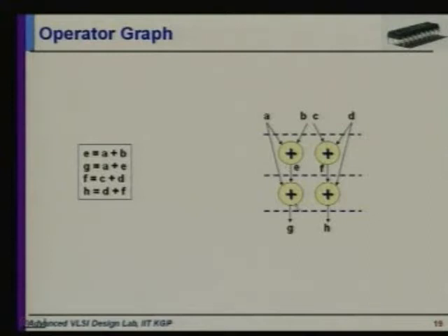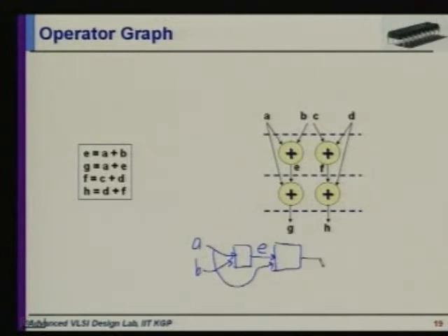How many are we requiring here if we use 2 adders? 2. If I give you 3 adders, can you make it better? No, because anyway you have to add these 2 first and then use the result in the third adder, right? What you could do, however, is take one adder and fit in A and B into it, and then take the output of that adder, fit it into the other adder, and then use A and E to go there, take G out of this, right?